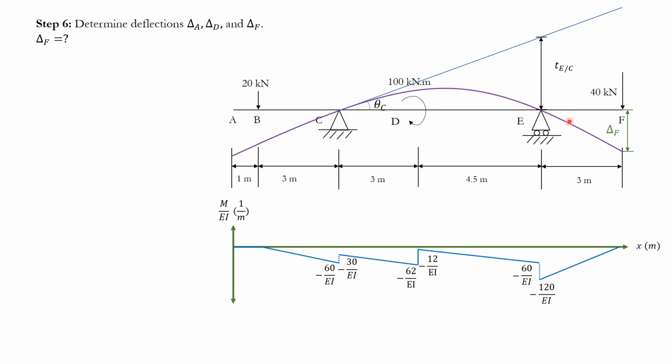So as you see, the procedure for finding deflection based on the moment area theorem is very similar across these multiple cases that we are doing. It's always figuring out where the deflection is exactly, figuring out where the psi is, and figuring out where the deviation is that we are taking. Also you can take any two points that you wish, but you always want to make your life easier. Of course, you could go with E. You could even go with A if you have it. It's fine. But first, you always want to be as close as possible to that point, because in that case you don't have to do as many calculations, but not at any cost, because in this case we don't know theta E. In that case you have to use the first theorem again, find theta E, and that's just too much hassle. So we went with the most efficient way to solve this problem.